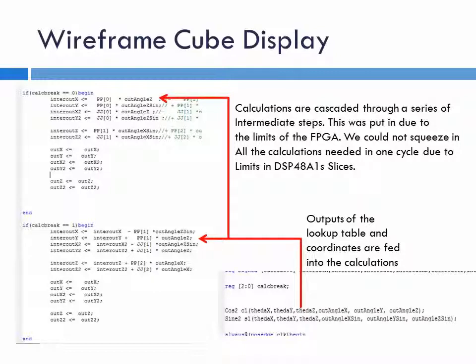We needed to break up the calculations into 4 separate steps because the FPGA we are currently using did not have enough slices to handle the entire matrix calculation for all 3 points in one go. Furthermore, when we first went with a single calculation clock cycle design, Xilinx did not catch the timing error, so many hours were spent before we caught the timing error ourselves.